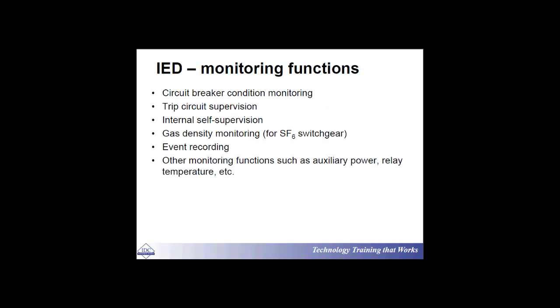Well, sometimes it is just monitoring. That's another story. Monitoring what? Monitoring, for example, if the trip circuit of the circuit breaker is healthy. It doesn't have any loose connection, any disconnection, any failure of the power supply. So what is the role? The role is trip circuit supervision. The role is TCS. Okay, so that relay, for example, is a TCS relay, or TCS element, yes.